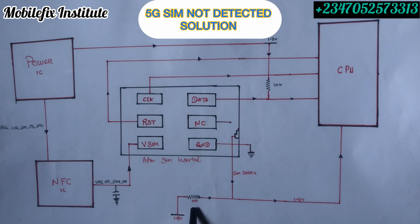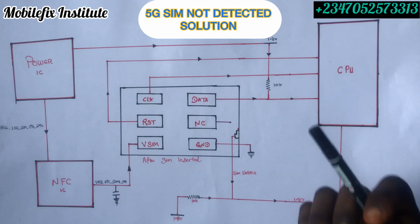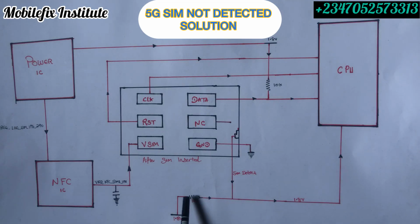And after removing the 10k, or before removing the 10k resistor, test this line. It might be faulty or might be open from your power IC, so it's not going to send this 1.8. When you locate this resistor, your phone is switched on. When you switch on your phone, you locate this resistor. Test this side of the resistor that is coming from your power IC. It should give you 1.8. If it doesn't give you 1.8, you work on this line.